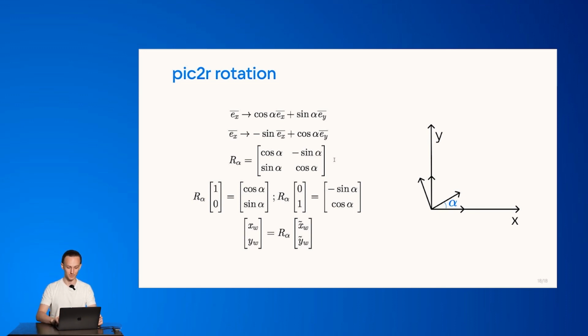We perform all those operations with calculating x and y without this angle, and then we just multiply this two-dimensional vector by the matrix of rotation, and after that we get the whole complete pixel-to-robot procedure with the coordinates of the object in the robot's frame. After that we can do whatever we want. We can plan the trajectory or kick the ball if it's near the foot already.